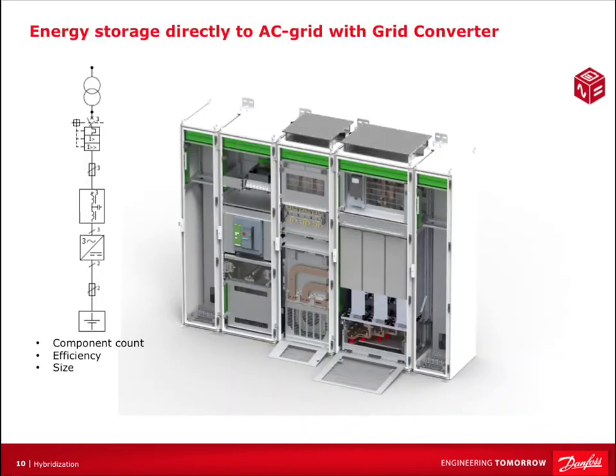If we wanted to take just a quick look at which components we would utilize in this situation, it's pretty straightforward. In this case, we would have some kind of a storage medium, and then we would need an AC grid power converter. If we were to look at a typical power converter, this would be something that we would typically deliver to our customers. This would be the grid converter section with some basic switchgear in front, and LCL filters here providing filtering for power quality back to the network.